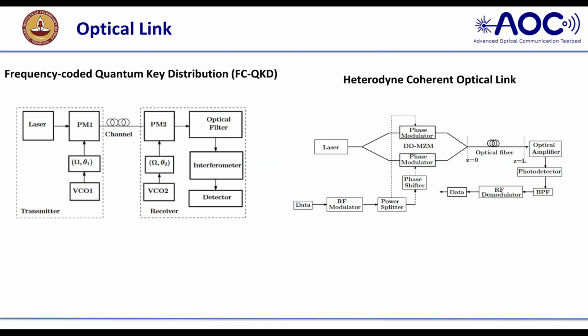When you see the semi-classical treatment, they talk about intensity, mod E square. But here I will treat light as particles, like balls, coming with particle nature, and look at how we receive the data and how the semi-classical and quantum pictures deviate from each other. In physics, they do not worry about phase noise and so on, right? But from an electrical engineering background, we should worry about the intensity noise created by the laser, the optical amplifier, and the RF source, and the intensity signal-to-noise ratio will not be that much of a problem when using an amplifier.